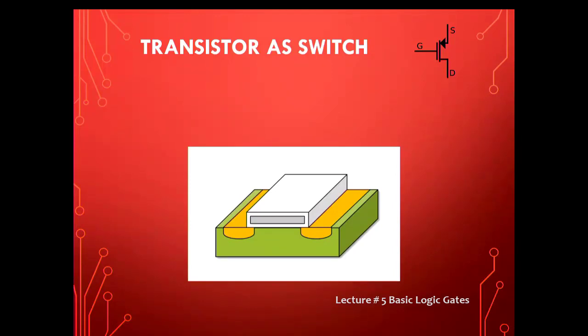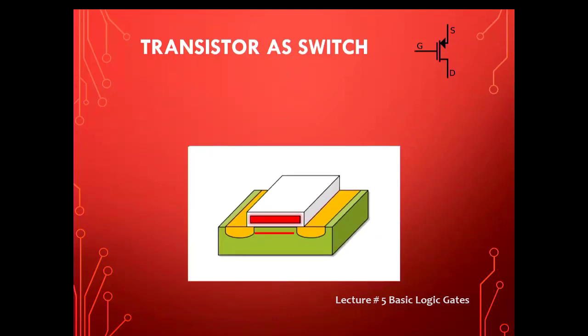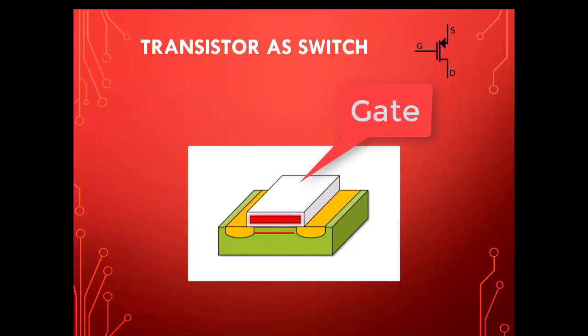So glass is being used as an insulator, and this gray rectangle box is basically a metal, and you place that material on top of those yellow regions. We refer to this as a gate, and when this gate is energized, or in other words an external voltage is applied, it creates a conducting channel allowing the electrons to move from this yellow region to the other region.